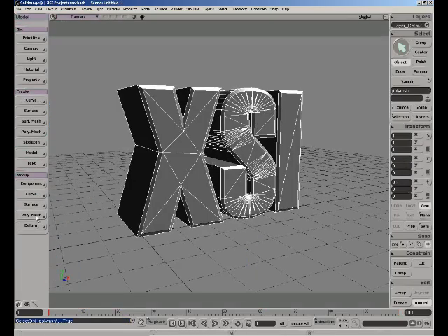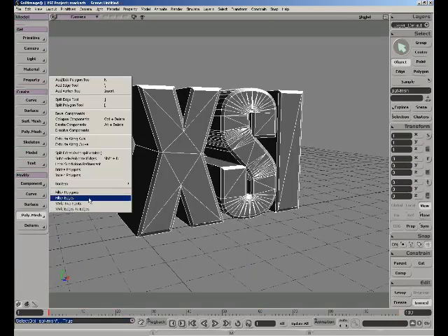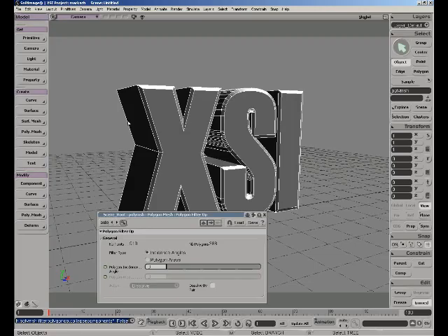There's a new filter polygon tool within XSI that allows you to easily do polygon reduction. We have filter polygons and filter edges. I'm just going to quickly apply that, and you can see it automatically strips all that extra geometry off there. And then you have a slider which can even let you get more detailed if you'd like. You can base this on the incidence angle, the polygon area, and then of course with the other tool you can focus just on edges.